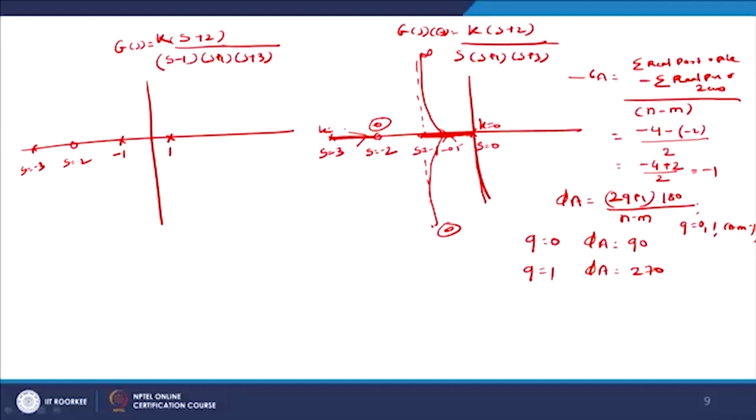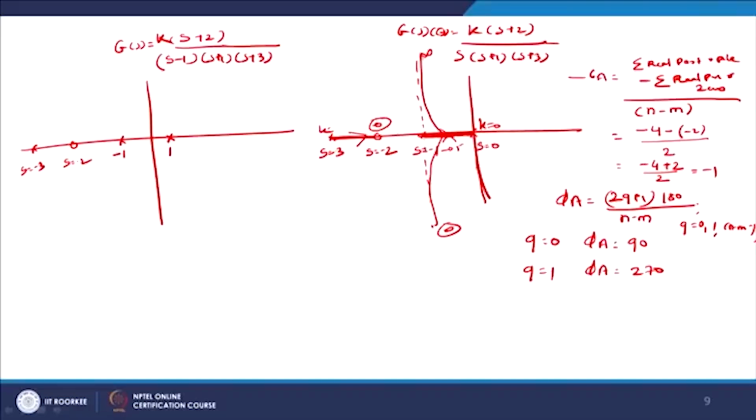Sometimes it happens that students are working on some project, and in simulations they are getting results. But when they implement the same thing in real time, they say that results are not coming, because in simulation we are getting results, but in hardware, real-time results are not coming. So if you use the classical approach, this can be a possibility. So here also we will find that in this particular example, for k varying from 0 to infinity, your system is stable. But if you take this example in real-time applications, this is not possible, the system is unstable.